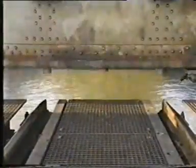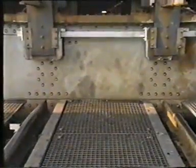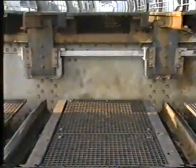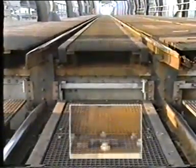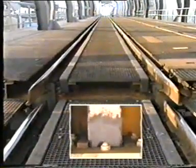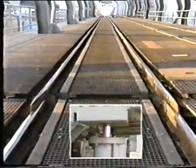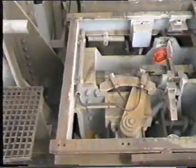If the bridge is open to traffic, the deck must be fixed vertically and brought in the correct position in the longitudinal and lateral directions. By means of overweight of the deck or a locking pin, the vertical position can be fixed. A pin necessary for centering in longitudinal and lateral direction also adjusts the rails. Buffers reduce the kinetic energy just before the bridge touches the supports. The locking pin fixes the bridge vertically.